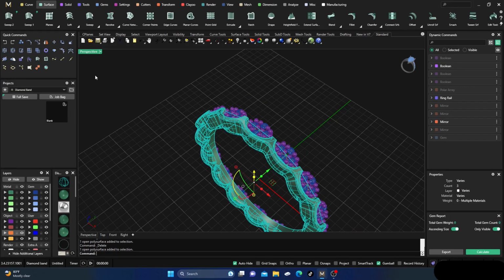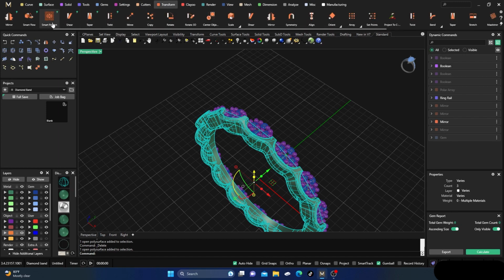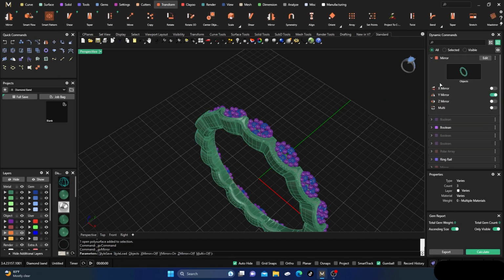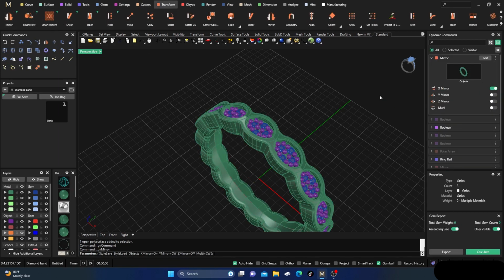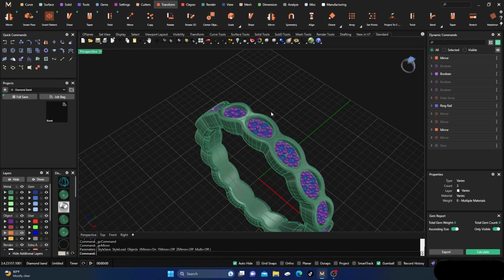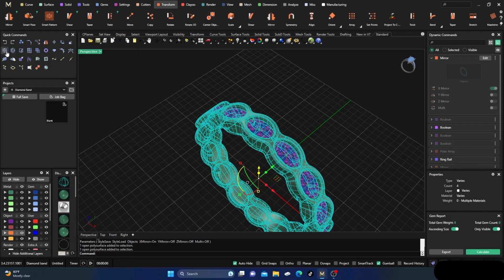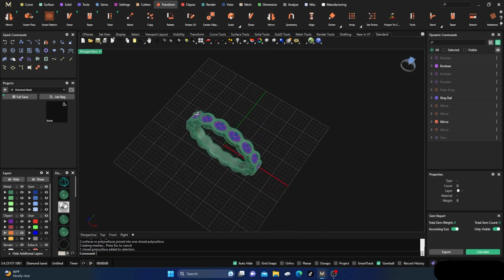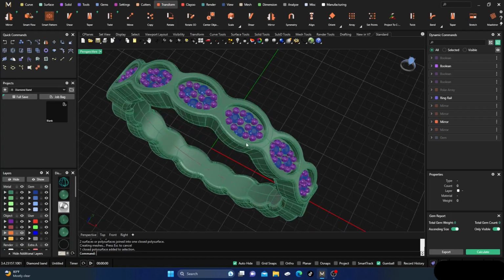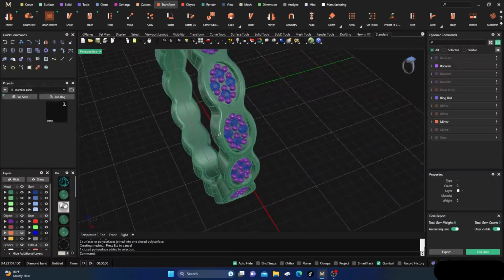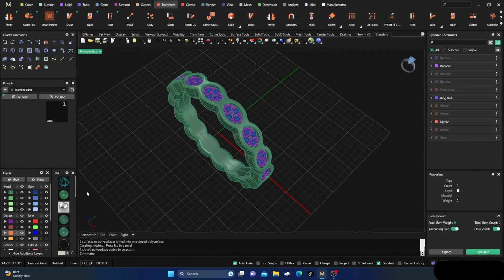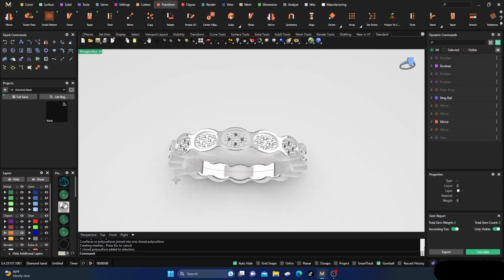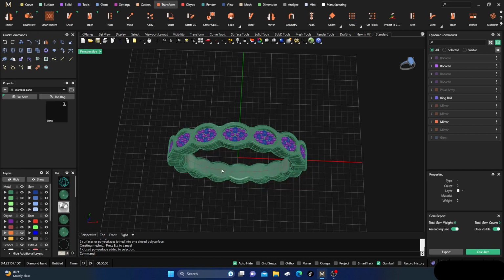Click on this side, and we'll just do a parametric mirror in the X direction, not the Y, and then hit enter. All right, and I should be able to take those two and join them together and check it, and we have a closed polysurface. So we are good to go. That's pretty much very nicely done, right? Very quickly. And everything's all joined up there.